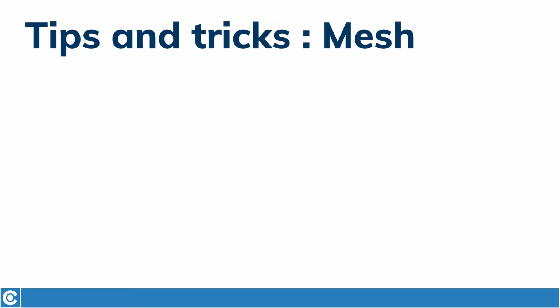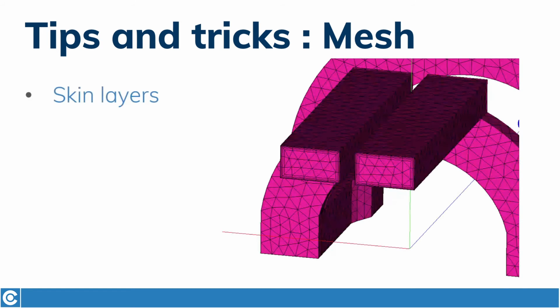When it comes to meshing, there are mainly 2 things to remember for those who are using Advanced Geometry Editor. Always create proper resolution for the skin layer in inductor and workpiece, because without it in mesh, the electromagnetic and thermal results of the simulation will be incorrect. Don't get confused when you see viscous layers function to resolve the skin layer. This is simply an analogical tool from fluid dynamics which is used for mesh layer creation in our mesh editor.